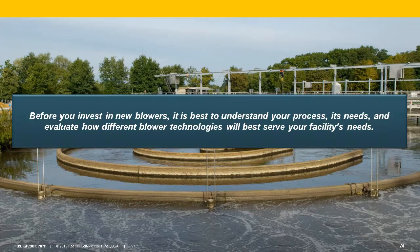Okay, so hopefully these three exercises demonstrated a valuable methodology for evaluating blowers. While working through these scenarios, we learn how the application or the process can impact your decision making. Additionally, modeling your process can provide insight into how the prospective blowers will operate within your system. Most systems are dynamic, so static evaluations do not accurately represent how the units will be utilized. Generating a model that accurately or partially represents your system or process can allow a more realistic machine evaluation, which will lead to a better blower selection.